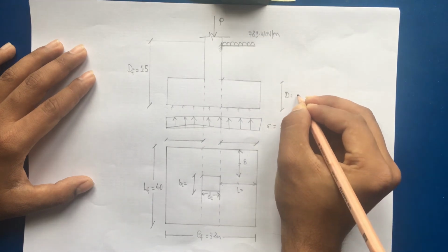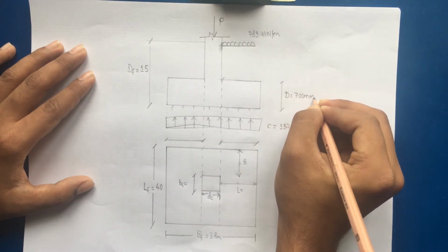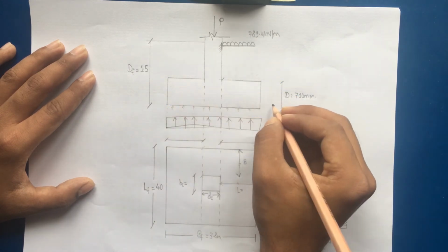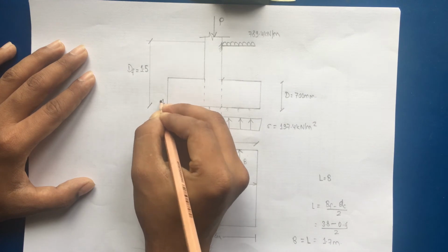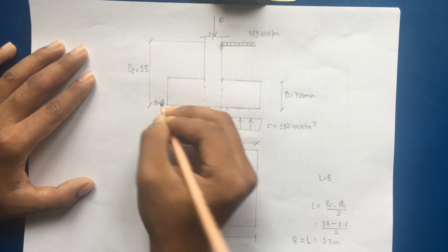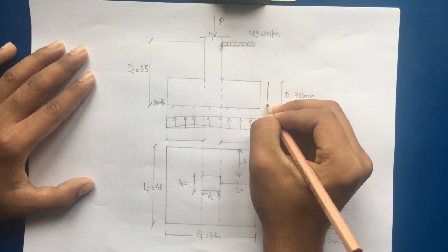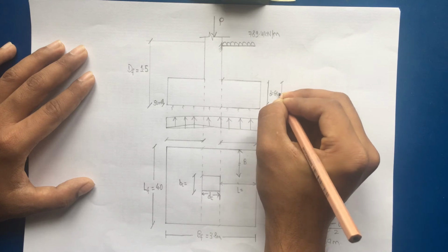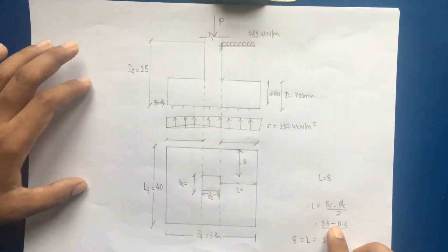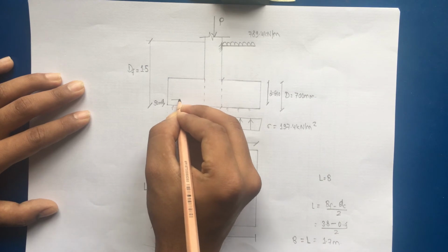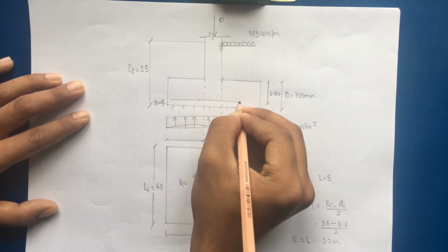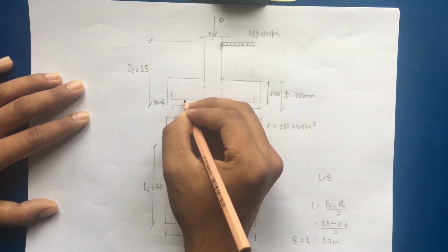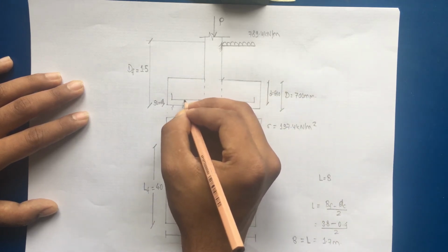You have to understand the value that we have taken for B, which basically means the resisting width. In our case, that is the pad footing, the whole width of 4000 mm is available for resisting the bending moment, whereas in the sloped footing, the resisting width may be taken as the width of the column plus the extra width, that is the offset provided in the footing. So that is the difference while taking the value of resisting width. So we have taken 4000 because the whole length of 4 meter is available for resisting the bending moment of the bar provided.